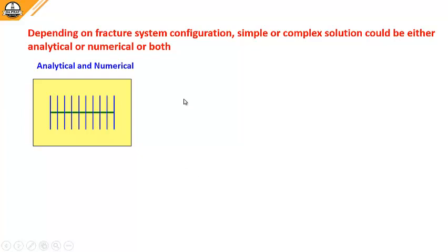So depending on the fracture system configuration, simple or complex, the solution could be either analytical or numerical or both. According to microseismic, you can get an idea of the configuration of your fractures.